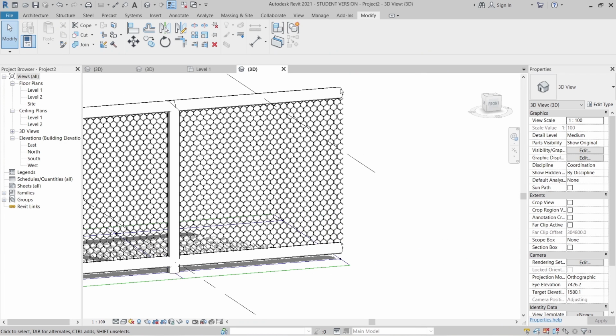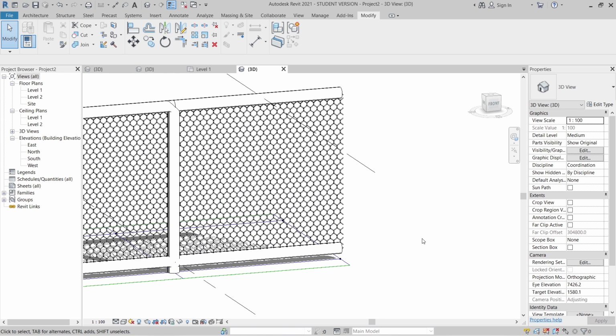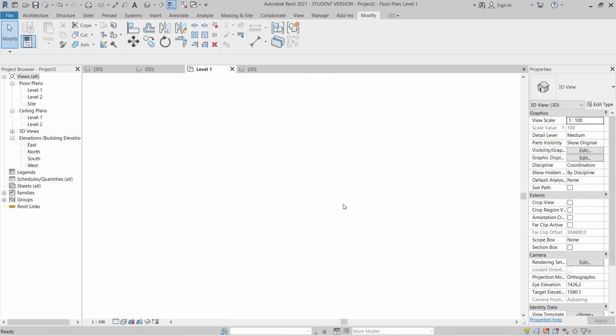And of course, for the final part there, you can create another pose by using our generic model pattern base or adaptive component, just using plus our 2 points there to finish the rest. And sometimes in my case here, I just want to lift it like this because here will connect until my wall there. I just create another wall. It's done already. Let me go to my level 1 first.